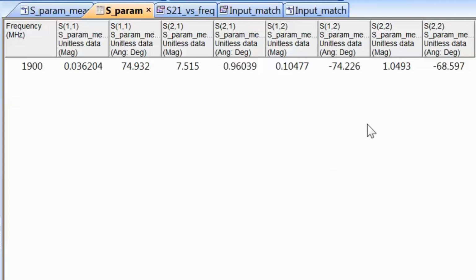There is always some level of instability with the transistor that has to be sorted out before we carry out our design. So what we want to avoid is having reflection coefficients, both at inputs and outputs, being greater than 1, because this is bad news for the transistor. It can create oscillations or even destroy the device.